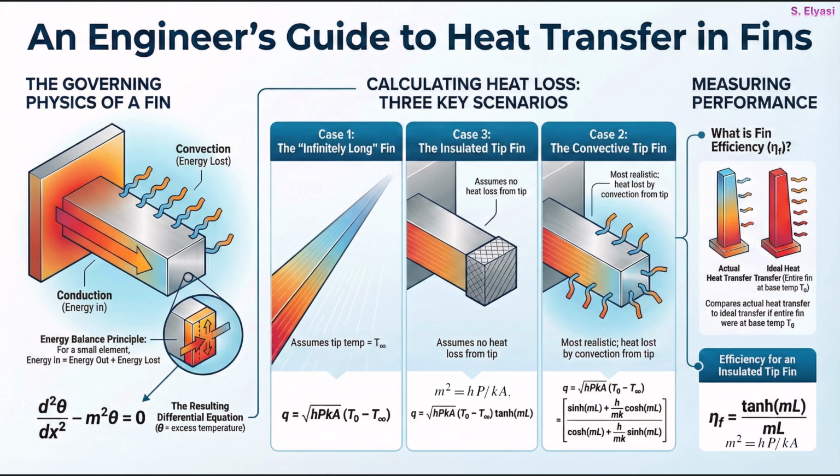And finally, how do we know if a fin is any good? Well, that's where fin efficiency comes in. It's basically its report card. It compares how much heat the fin actually transfers to the absolute most it could possibly transfer. That perfect scenario? That's if the entire fin somehow stayed as hot as its base. So, efficiency tells you how close to perfect you're getting. Grasping that energy balance, the different tip scenarios, and what efficiency really means gives you a fantastic foundation for analyzing pretty much any fin design out there.